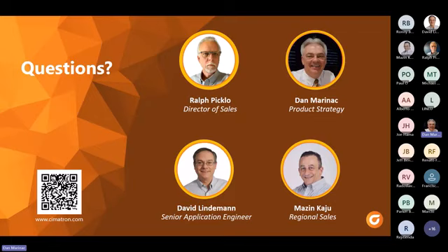These are typically higher cost grades due to the complex mill processing that the steel mills provide to produce them, as well as being highly alloyed, the latter of which leads to welding challenges. Here you're going to find a lot of your dual phase and higher strength steels. When you get to the Gen 3, that's an advanced high strength steel that starts to enter into the multi-phase category. And this is a highly engineered material for enhanced formability.